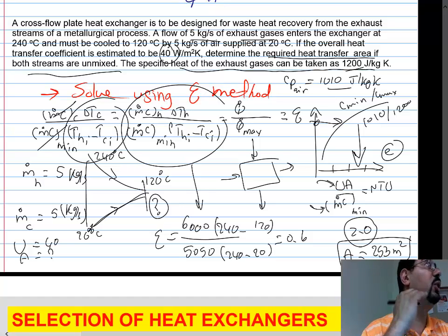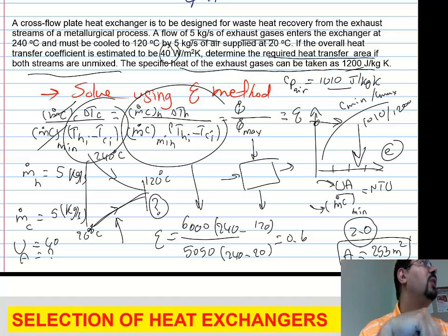And so if you really want to do this accurately, you assume what the T mean is, and you calculate CP at this temperature. And once you come up with the temperature at the end, you go and say, well, actually the T average was not what I assumed. The T average is something else. Will the CP of the air become any different from the number I used? And if the difference is big, you go again with the right CP, and you do the problem one more time. This is to be accurate.